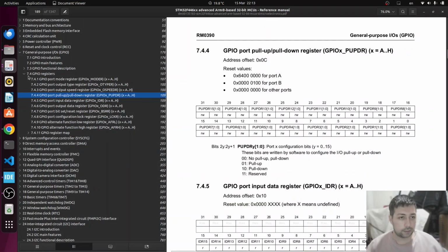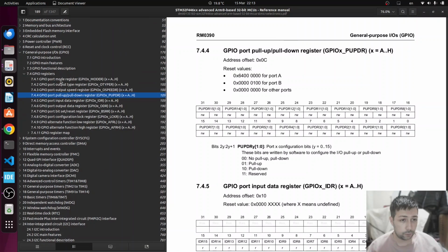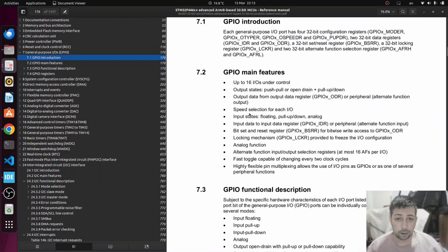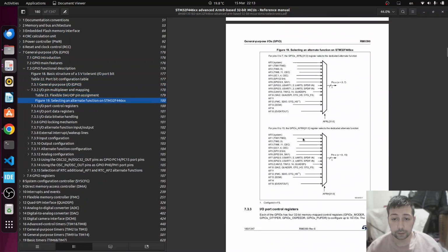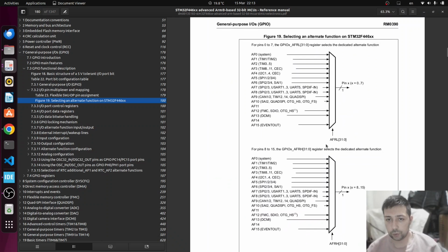And let's get to the alternative function side. So before that, I have to open alternative function. Yes. So as you know, I2C1 we will use PB8 and PB9.